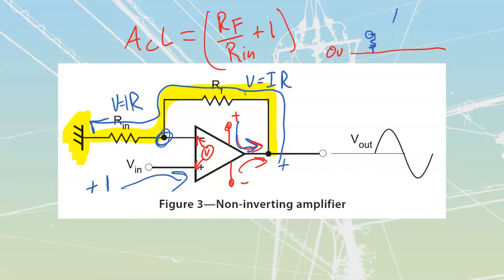And really what we end up having is both of these start to float up above here. The top one is my feedback, the bottom one is my input value of resistance. We are going to continue to raise this top point until eventually it becomes level with whatever my input value of voltage is. It's always going to end up with about this plus 1 volt differential, just because we've got some internal drops across my actual components inside of there.